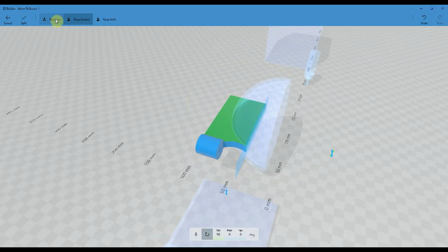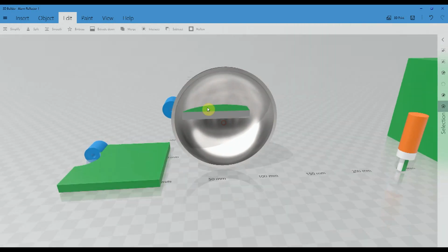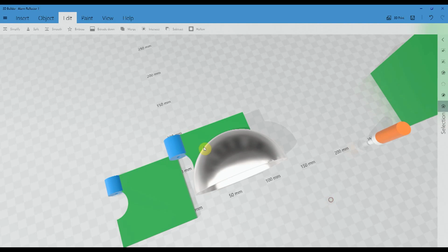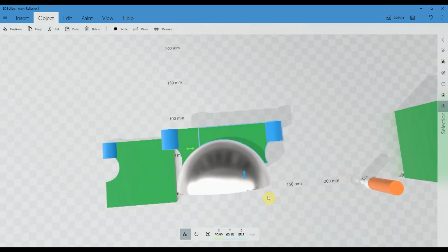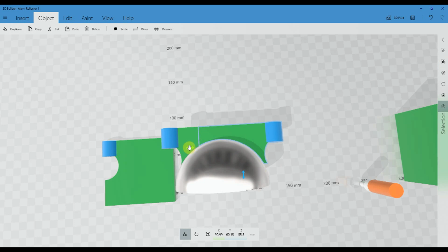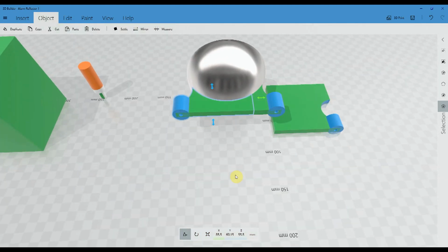When you rotate any object in 3D Builder, it's rotated about its centre, which you don't necessarily want. So what I'm going to do, the trick I've found in lots of different designs, is you produce a duplicate, mirror it, and then you group it with the original. So if you like, you're creating the centre where you actually want the centre, and then when you rotate it, it rotates where you want. And then after you've got that done, you can then delete the bits you don't want. So I'm using the group command. Once I've lined up both sides, the group command's on the right hand side with the other select and deselect tools.